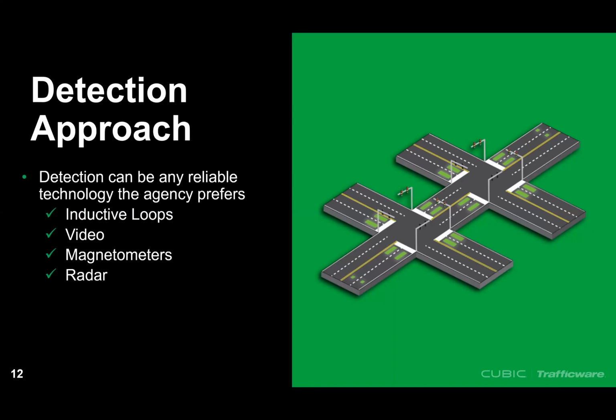As you can see there, if the intersections there in the middle are closely spaced, then advanced detection isn't really necessary, meaning that intersections that are close together, the offset adjustment is not something we're really required to adjust much to get that progression we need.